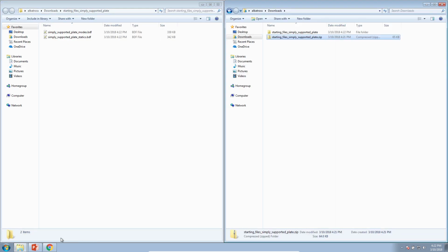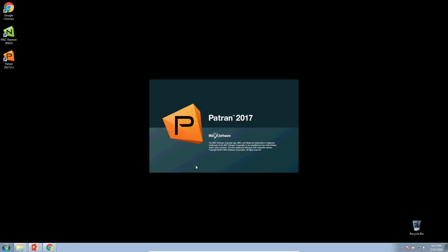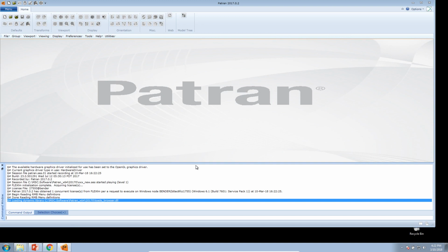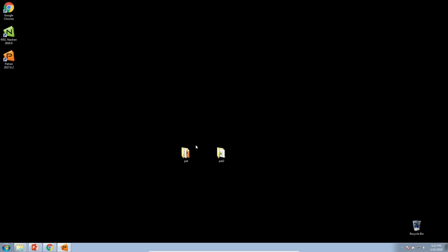I should also add that you can build your starting design model in your traditional preprocessor. Here I'm using Patran, so I'll wait until later to import the model. What I want to say is that you may have your own model you want to optimize for topology optimization. When you are finished creating your model, it will produce a BDF file that you can use as a starting point for your own topology optimization.